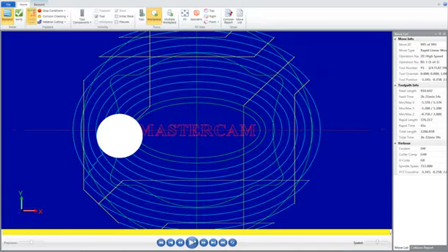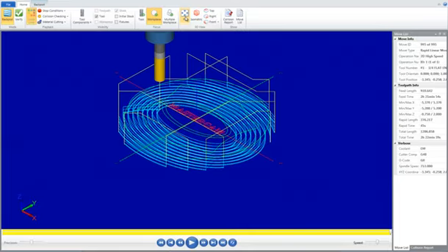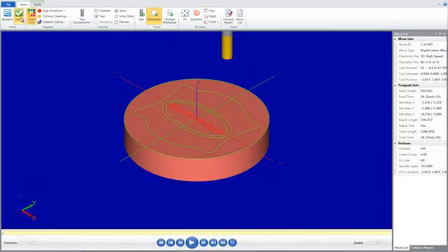To view your part, select the isometric view and Fit icon. Your toolpath will appear as shown. We will now simulate the toolpath and verify. From the Mastercam Backplot Home, select the Verify button as shown. Verify mode shows the path the tools take to cut the part with material removal. This display lets you spot errors in the program before you machine the part.